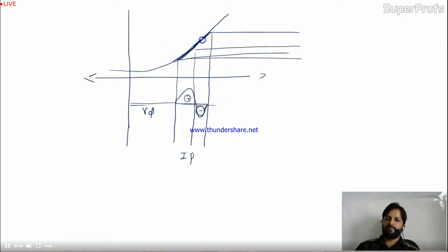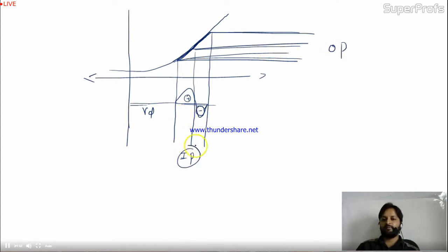If this full part is covering the input and the output also I'm getting the full lines, means full mapping. The output mapping is completely equal to the input mapping in this case. What is the case? First you should choose the linear region like this, and second you have to add some DC part so you can shift your input. Why are we shifting the input? Now if you get the output, your output will be a complete replica of the input. Okay?